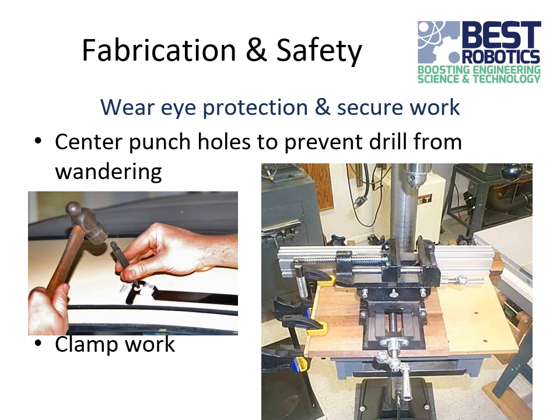For drilling, and this is especially true if you're using a hand drill, it's a good idea to center punch your holes ahead of time. What that does is put a little divot there that the point of the drill can rest in when you get started. Otherwise, the drill has a tendency to wander, or walk around a little bit, before it really starts digging into the material.